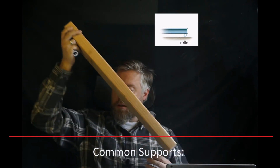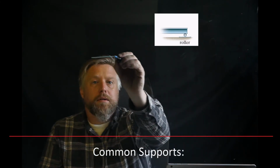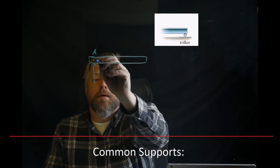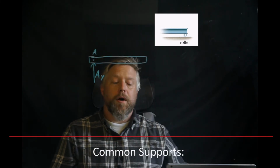So what do we do to replace this support on your free body diagram? Well, if we have that 2x4 drawn as an object here, we're going to restrict it from going down. I'm going to put an arrow up. I now have one unknown, and if this was at point A, I would call that AY, because it's going to restrict the motion in the y direction.